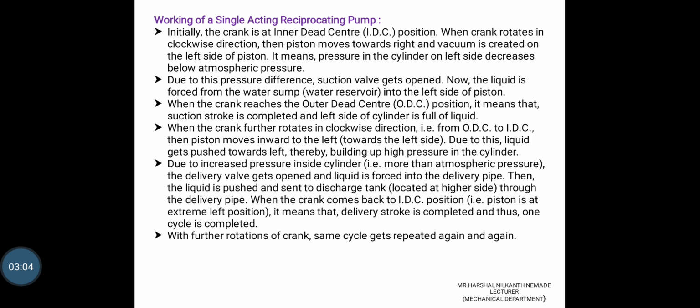Due to the pressure difference, the suction valve opens. Now the liquid is forced to enter from the water sump or reservoir into the left side of the cylinder. When the crank reaches the outer dead center position, ODC, it means that the suction stroke is completed and the left side of the cylinder is full of water.